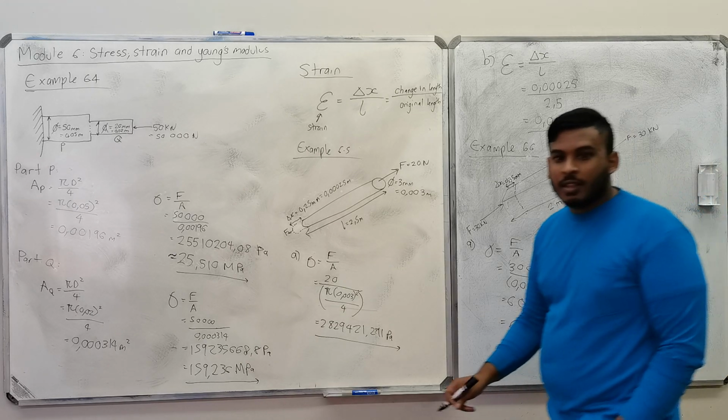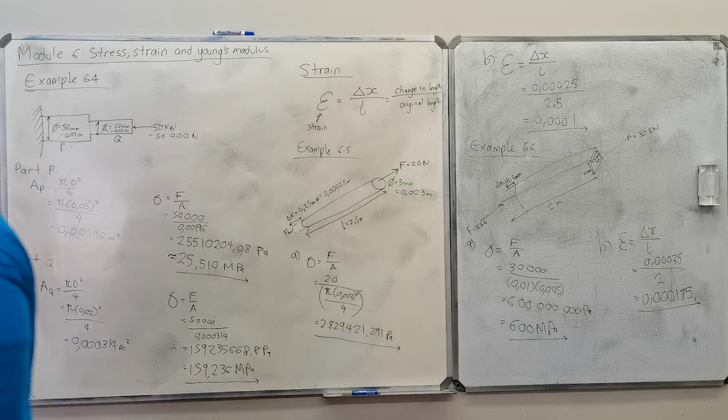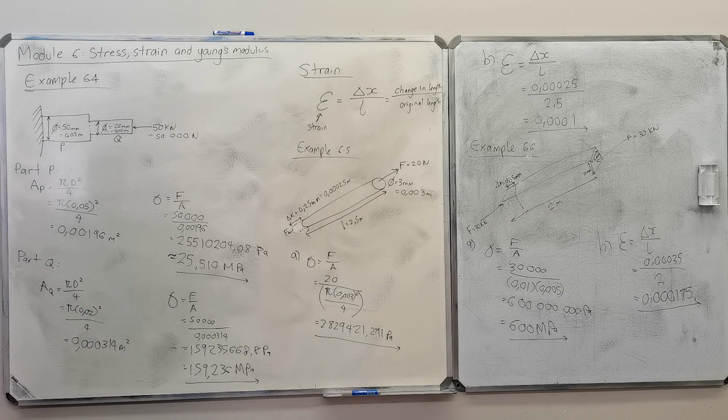They got the right answer here, but they got 0.35 divided by 2,000. They made the meters into millimeters. Because remember, it's ratios, so you can change the top one and the bottom one in the same way. But if you start changing your units, somewhere along the line you're going to mix it up and mess it up. You'd rather just stay with the meters.